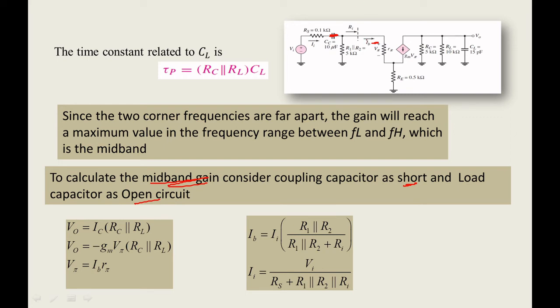What do you want to find for this part? That means you want to look at the opposite resistance. What is the opposite resistance for this resistance part? This one, right? That is R1 parallel to R2, divided by R1 parallel to R2 plus this Ri. That's all. So it is something like R1 parallel to R2.